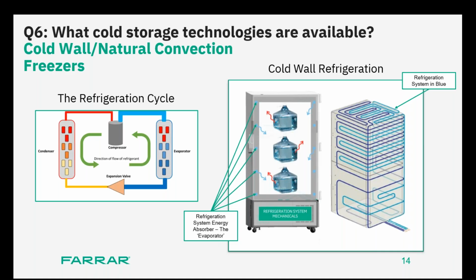So depending on your application, Rebecca, people have different configurations. If it's a large system, people usually use a thermostatic expansion valve. For most of the standard ULTs, it's a capillary tube. And there's a very sophisticated option called electronic expansion valve, which actually meters out the right amount of refrigerant based on your sample load in the freezer. And fortunately, Trane Technologies uses that for some of their freezers.